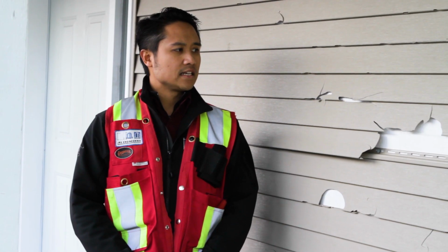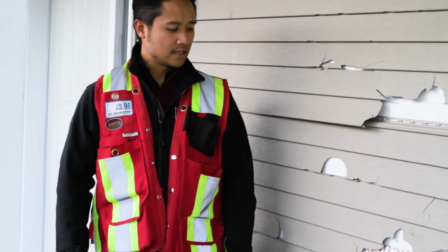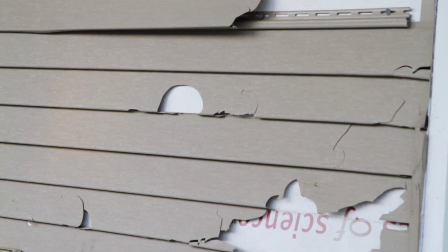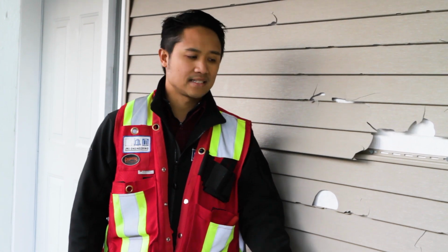One of the easiest things to review on a house is wall cladding. Now in this particular case, there's a little bit of damage, probably from a combination of people playing sports and the UV. We are on the south elevation, so it will see a little bit more sun, but we do want to keep the cladding intact for a few reasons. We want to try and minimize the air, moisture, and vapor that go into the wall assembly, and we also want to mitigate the amount of pests and insects that get in here.